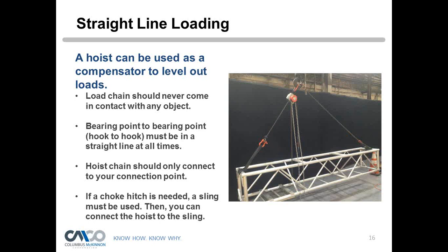The hoist should only contact your connection point. So you can see we've used a sling. Now slings are meant to be able to do your proper hitch. So you want to use the proper hitch or proper connection with your sling, take your proper reductions with your sling, and choose the right sling for the job.